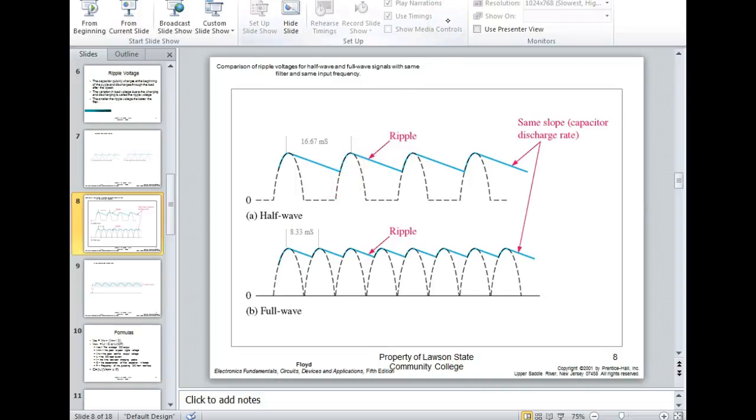It charges back up. And of course, for half wave at 60 cycle, we're going to have to size the capacitor to run the load for 16.7 milliseconds. And for full wave, we're going to do 8.3 milliseconds. And all you have to do is take that formula and rearrange it and say, okay, this is how much ripple voltage I want at this current, and then solve for C. And then you can size your capacitor. And always do what with it? Go higher, yeah, at least.